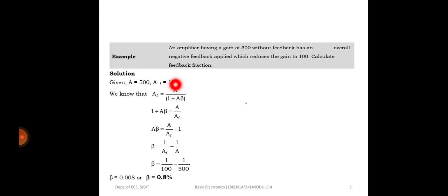Now let us calculate the feedback fraction. AF is equal to A by 1 plus Aβ. Substitute that and solve for Aβ and then for β.